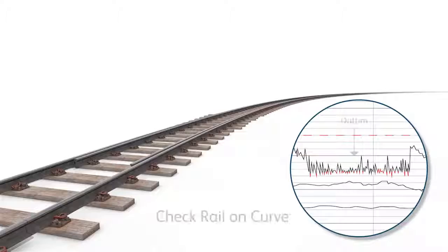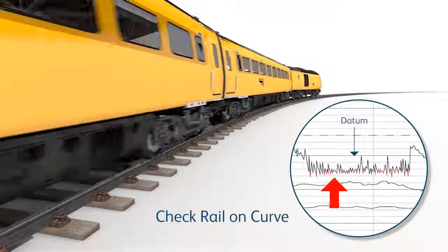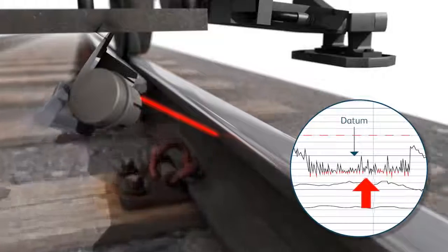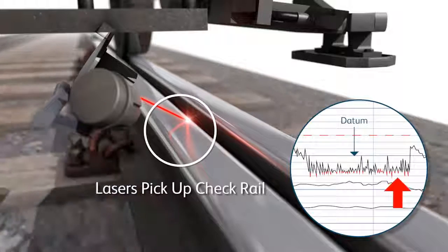On a tight radius curve, it is likely that a check rail has been installed. If over time the low rail on the curve has head wear, the TRV can show a length of tight gauge throughout the curve. The reason for this is likely to be that the check rail is less worn than the low running rail, causing the laser to pick up the check rail rather than the running rail.